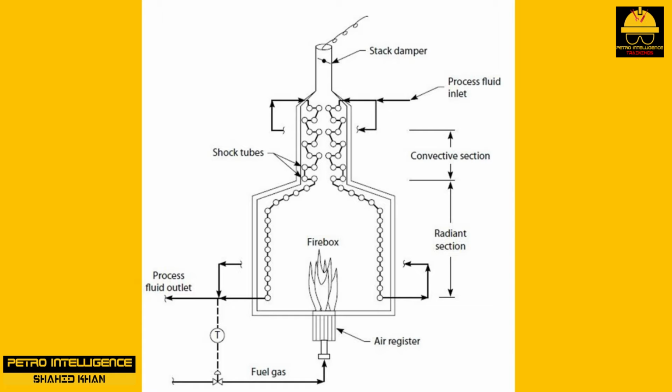This is because more heat is given to the process fluid and less heat goes up the stack. 2. The heater process outlet temperature declines as airflow is reduced past the point of absolute combustion as defined in the next section. In this situation we have products of incomplete or partial combustion such as aldehydes, ketones, and carbon monoxide going up the stack.